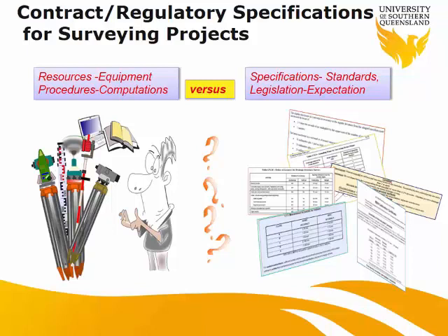Like if you want to achieve, for example, good height precision, say 5 millimeter, do you use GNSS for that? I would say no. So this decision making is part of our surveying job, that we have to be aware of and complete in a good manner, otherwise you're going to mess up the whole project. You're going to spend lots of time going out there, doing the job, and can't get the required specification.